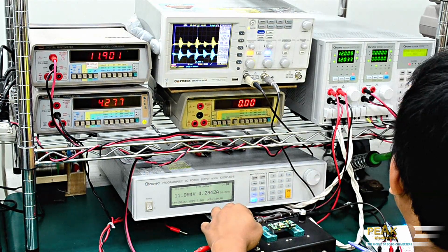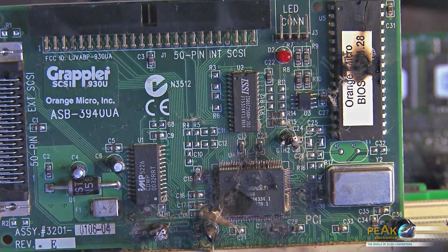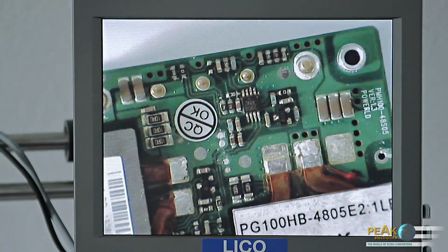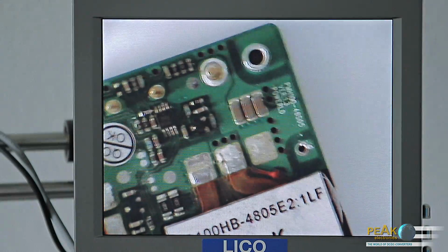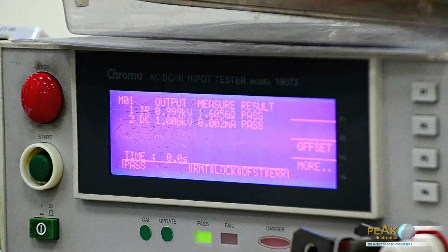First, the overvoltage. If a risk exists in an application that the DC-DC converter, even if only for a short time, is exposed to a high input voltage, for example due to voltage spikes, a transient voltage suppression TVS diode is fitted as effective protection. The response value, Zener voltage, of the diode should be at least 20% above the maximum expected operating voltage.